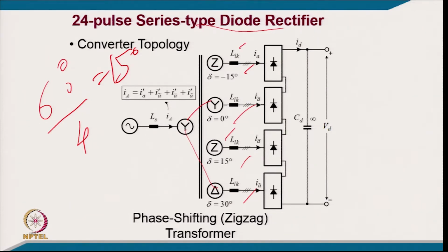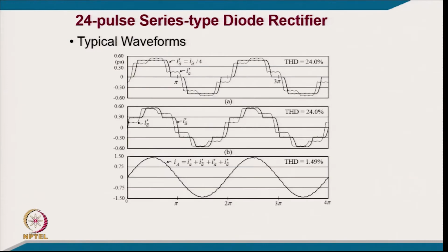Of course, there are many other connections possible also, and you are connecting all of them in series. So, all will have the same current, but when it gets reflected in the supply side, all these currents will be added together with the turns ratio correspondingly. So, you will get quite a good, let us say, THD, and you can see how this is 4 converter,